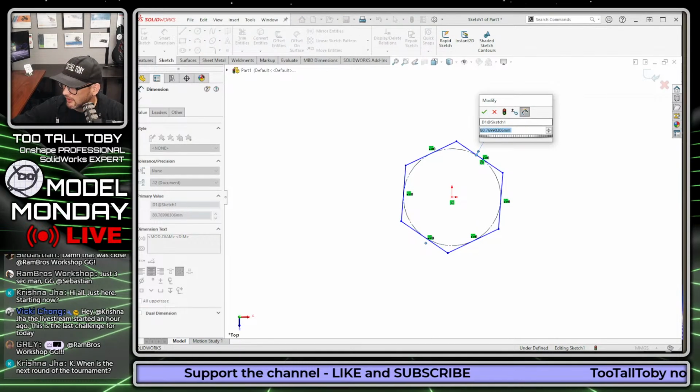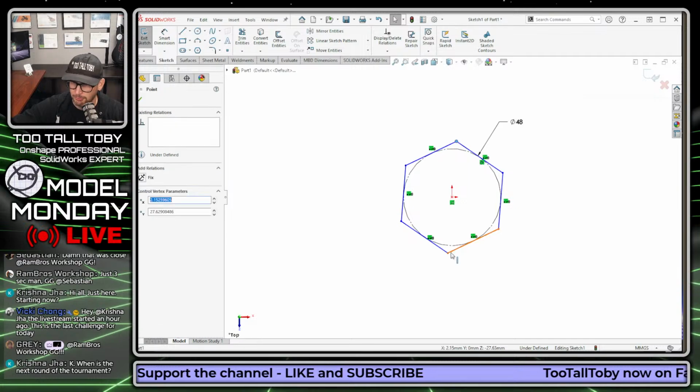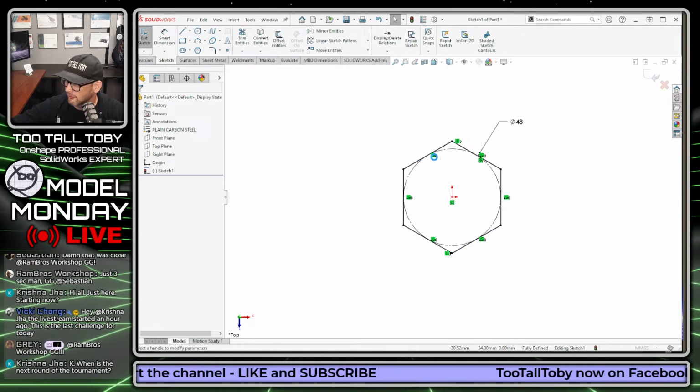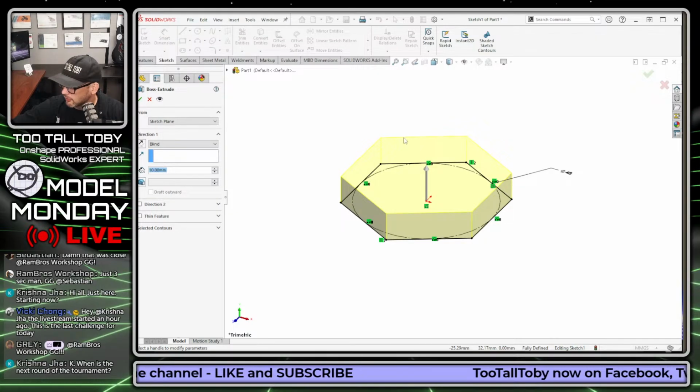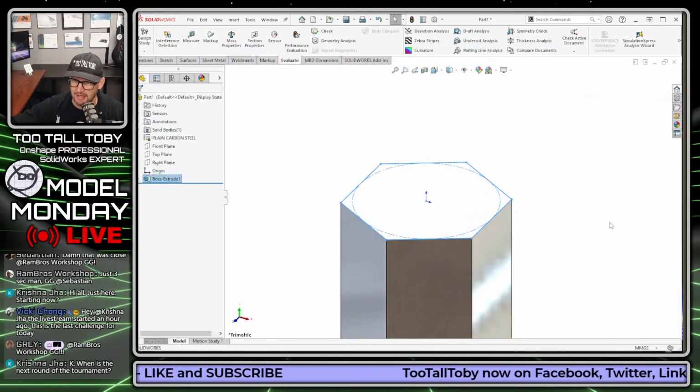The size of the hex there is going to be 48, and it looks like this point and this point are going to be vertical. So pick one, hold control, pick the other, make vertical, S key, extrude. And then this is going to go out to a depth of 70, shown there on the front view. Right click, reverse direction, right click again.